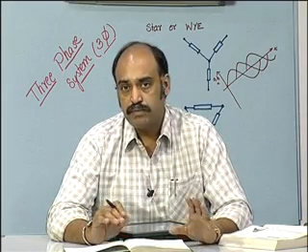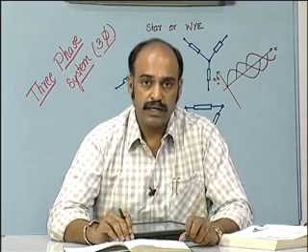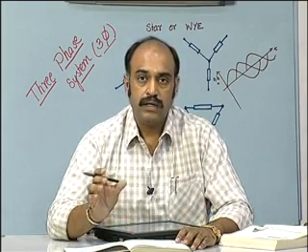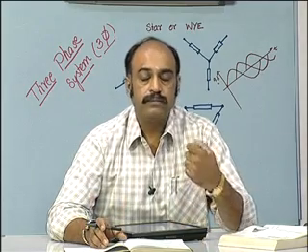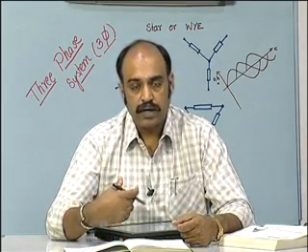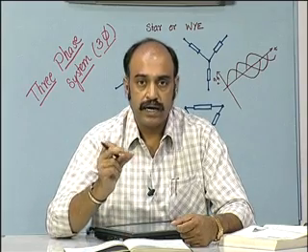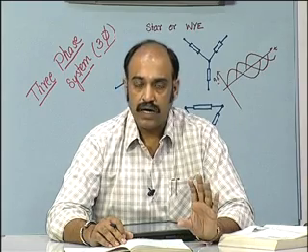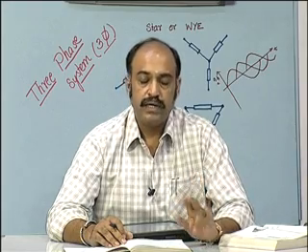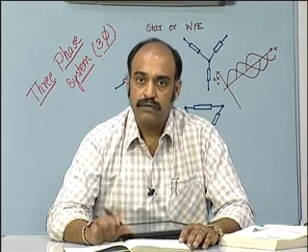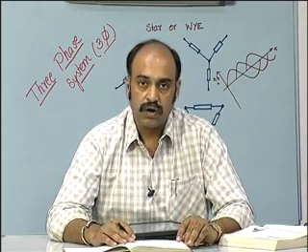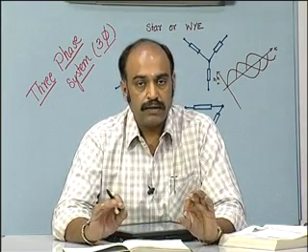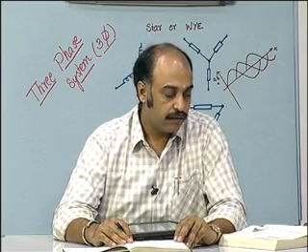The other method is by using watt meters. One may use 2 watt meters in the case of a 3-phase 3-wire system, that is, where neutral is not available. So, one watt meter may be connected to one of the lines, and the other watt meter connected to the other line, with the potential coils having the same third line as the reference. Then the values of the 2 watt meters are summed up to get the effective total power that is drawn from the source.